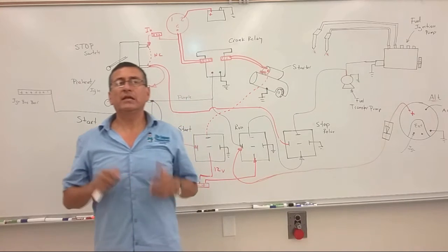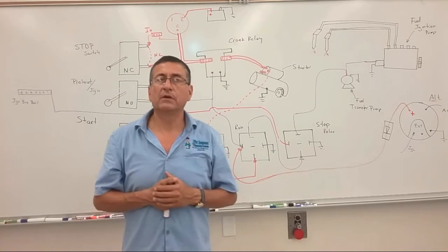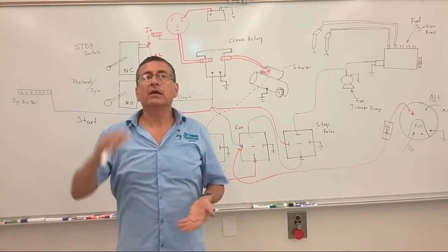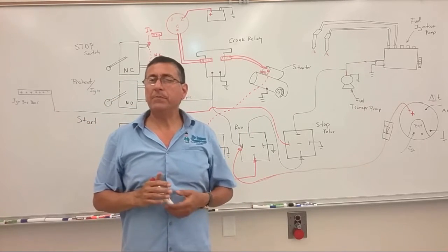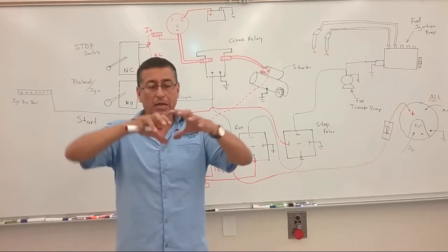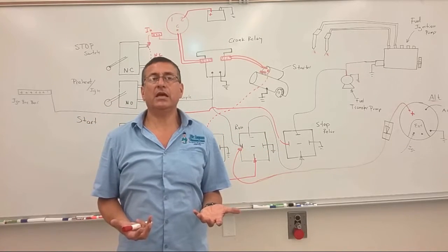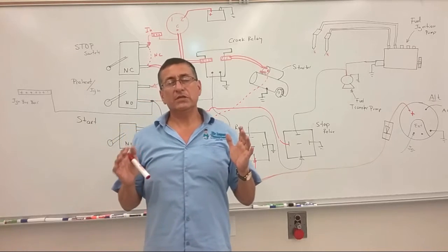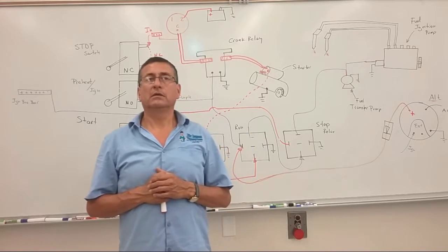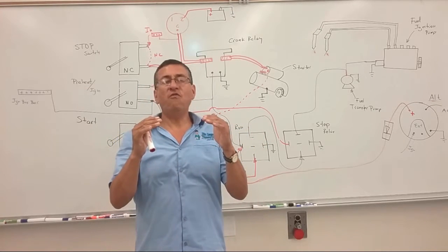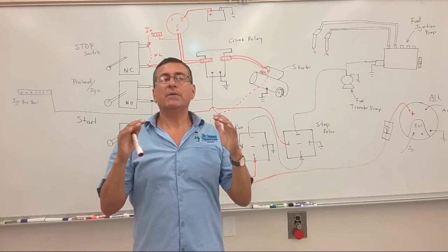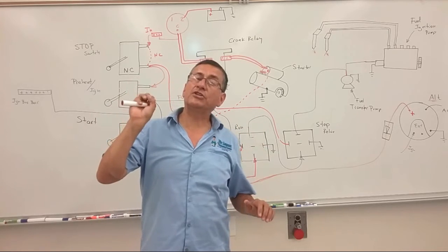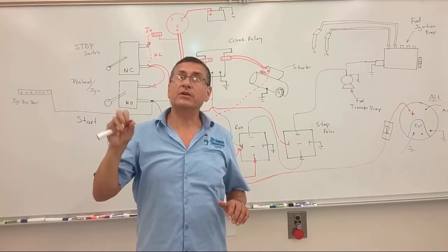In what other situation does the engine stop by itself? Yes, when the oil pressure internally goes below 40 psi. Internally in the engine, normally when the engine is running, the pressure is between 60 and 80 psi. When the pressure is below 35 psi, the majority of engines stop for emergency, and immediately you have a check engine code, low oil pressure.